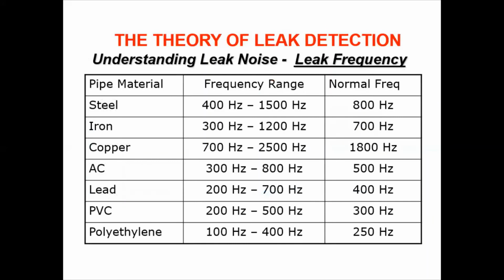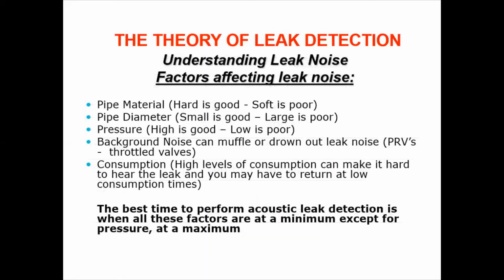Here's just a chart looking at some frequency ranges of leaks based off their material. And as you can see, steel, iron, very, very similar. Copper, very high, 1800 hertz. And then again, AC and lead and our plastics are much lower hertz leak sounds, frequency range.